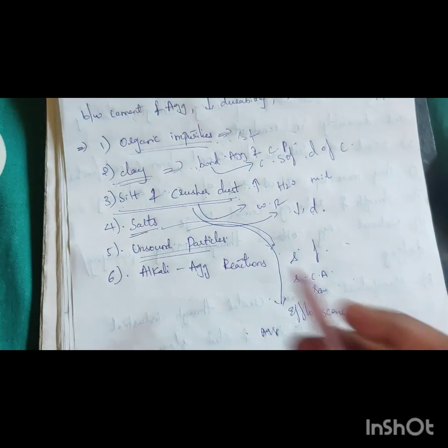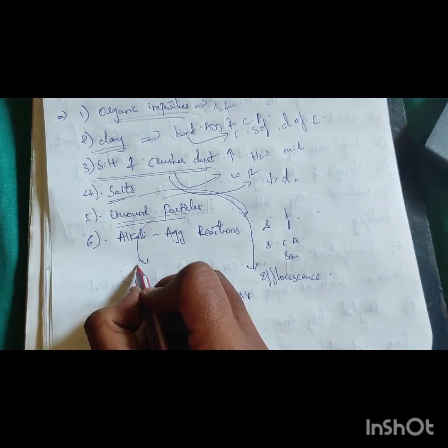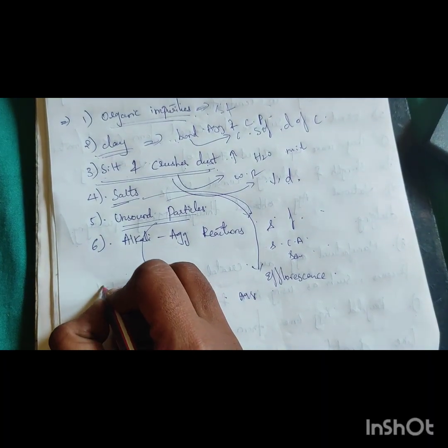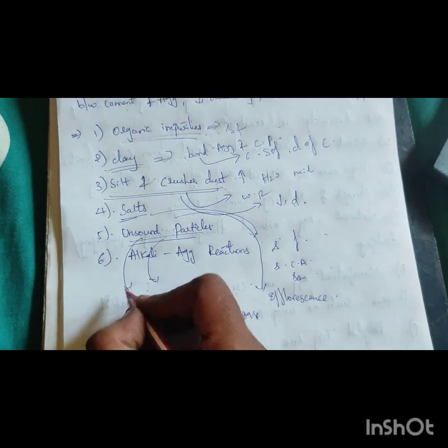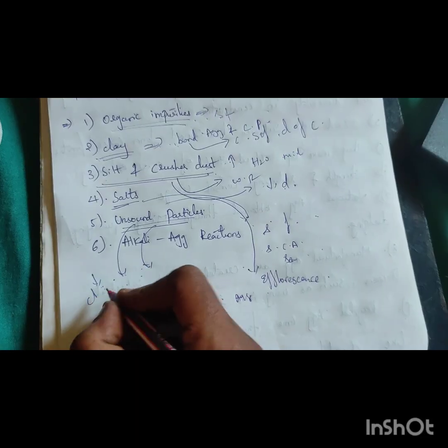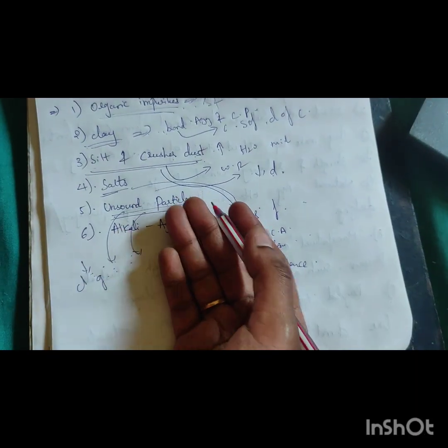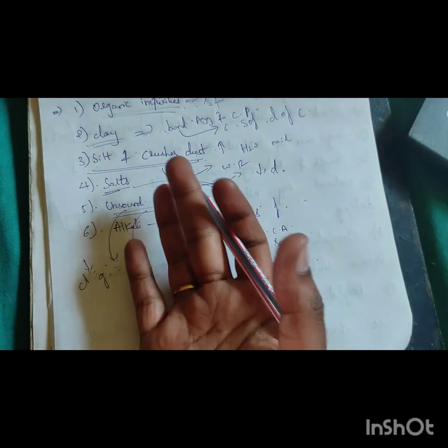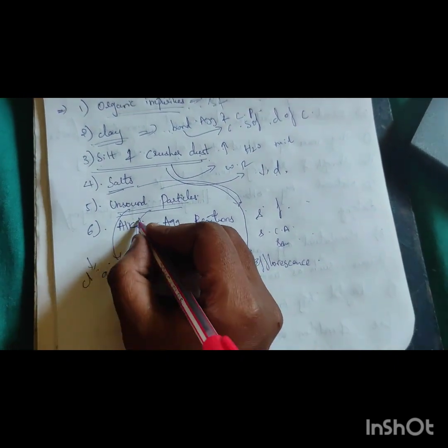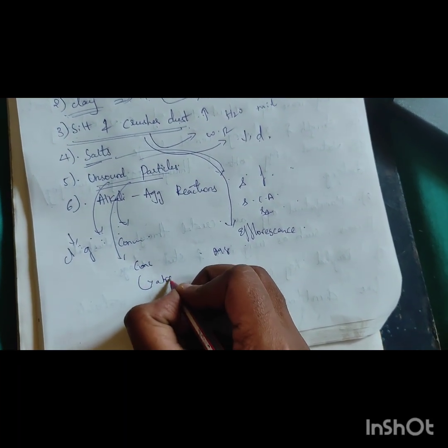The next one is unsound particles. These are materials that fail to maintain their integrity, and substances that lead to disruptive expansion on freezing or even on exposure to water. Shale particles with low density, clay lumps, wood, coal, mica, gypsum and iron pyrites are examples of unsound particles. If unsound particles are present in large quantities, over 2 to 5% of the mass of aggregate, they may adversely affect the strength of the concrete. These materials should not be allowed in concrete which is exposed to abrasion.